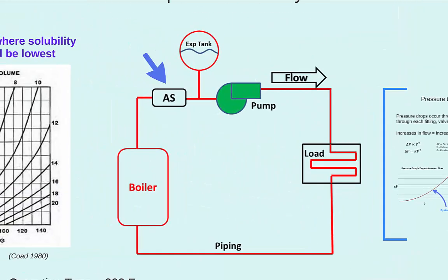Alright, the last component of these simple hydronic systems we have been looking at is the pump. The pump is the device that increases the pressure in the system, which will subsequently drive the flow of water through the system. The amount of pressure increase they have to add to the system will be equal to that of all the pressure drops in the rest of the system. Different pumps have different operating characteristics. That is, the pressure increase they provide to the system will depend on the flow rate they are pushing.